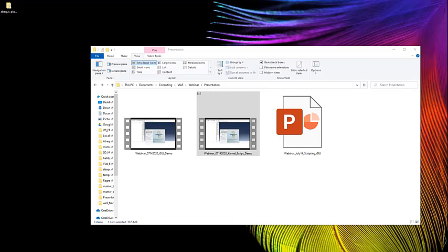Okay, as Syed had talked about, I'm going to transition a little bit to GUI customization. We were just talking about kernel scripts. Now we're going to talk a little bit about what you can do with GUI customization. What we're looking at here is a slide for customization with Abaqus CAE. We can develop a simple GUI or plugin through the really simple GUI plugin that's available within Abaqus CAE in the plugins menu. What this gives us is what we call a WYSIWYG, or what you see is what you get GUI. Basically, the inputs that are specified just get sent to the kernel.